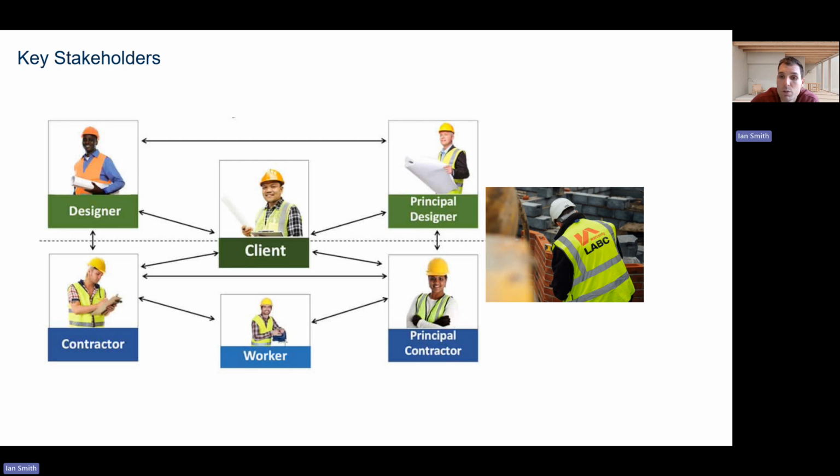Our last key stakeholder that we'll consider is our local authority building control officer. They will review the design and inspect the foundations during construction to ensure compliance with building regulations. They may require inspections before concrete is poured to confirm that reinforcement and excavation depths are correct. Their influence is essential because construction cannot progress to the next stage until their observations have been completed.